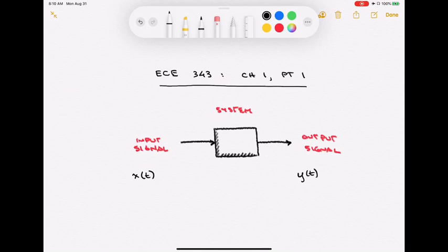We'll find out later that there's lots of ways of describing systems, but for much of what we do in this class, we're going to use letters H, either a lowercase or an uppercase, to designate something about that system. This is just the beginnings of our mathematical depiction for signal systems and their interaction. So I have a signal x of t feeding into a system H to generate an output y. If I wanted to start a mathematical description of this whole operation, then I might say something like this. I might say y, the signal, the output, is equal to the system H operating on the input x